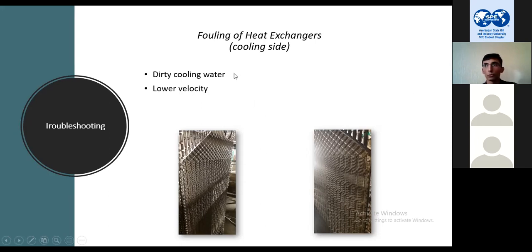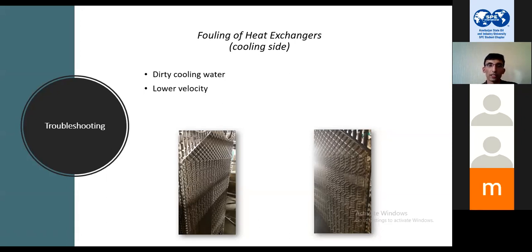Right now we're working on a change to remove that control valve from the cooling water and put it on the process water itself, like a bypass of the heat exchanger. Whenever we need to cool down the process water more, the bypass valve will close and let more water flow through the heat exchanger in order to be cooled down. When there is no need, the bypass valve will be opened, and this control should solve our problem.